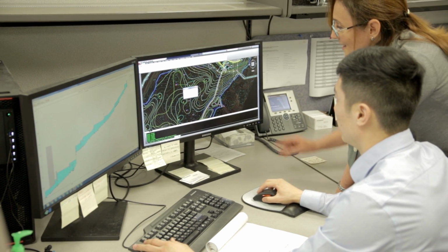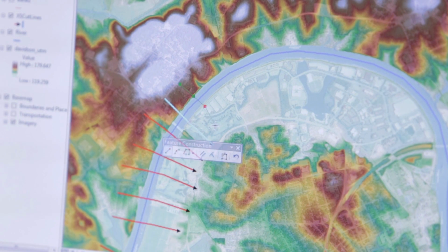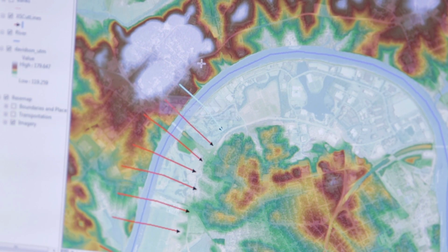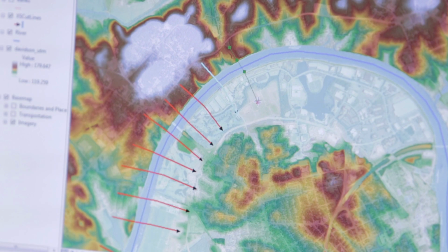The only thing a 1D model really calculates is how deep that water's going to get. It doesn't determine the direction. That is really down to the engineer to determine which direction the water's going to go, which is easy in most places. Certainly in mountainous areas, it goes downhill, confined within the embankments of a valley. And so although the 1D may be suitable in most places where you've got steep terrain, the 2D modelling can be very useful in areas where the flow patterns are very irregular.